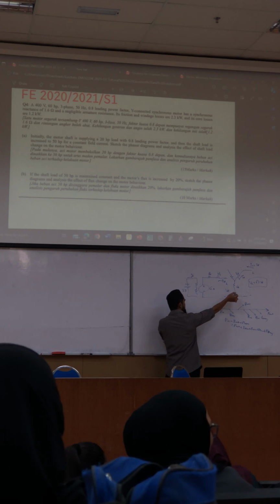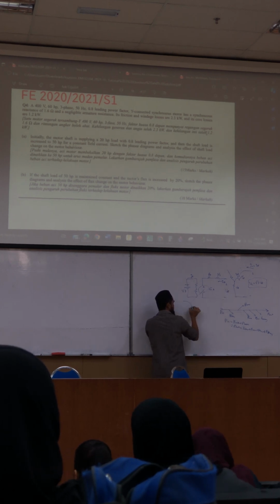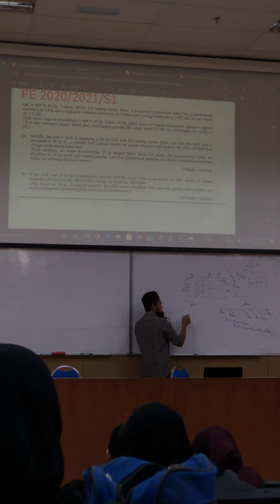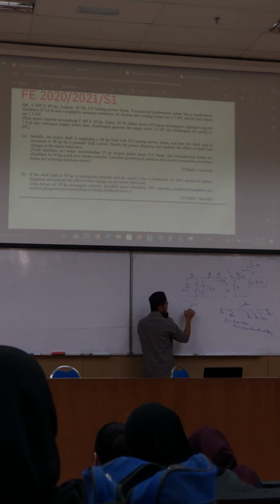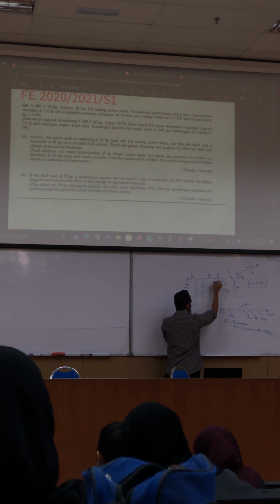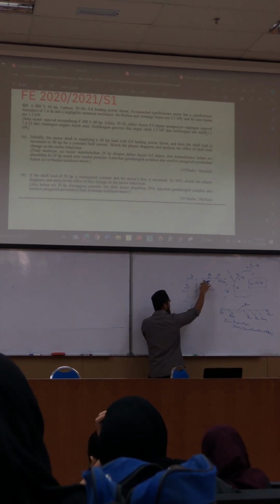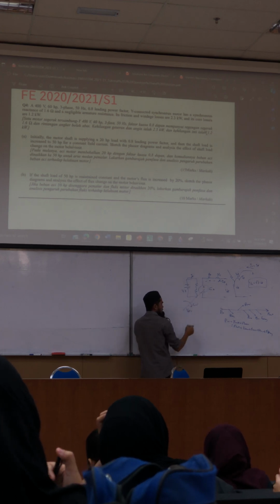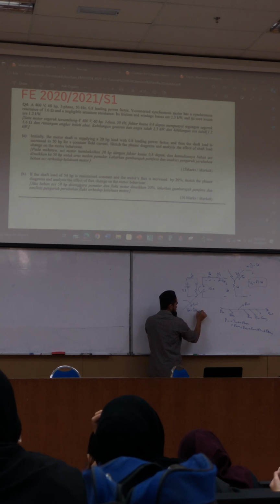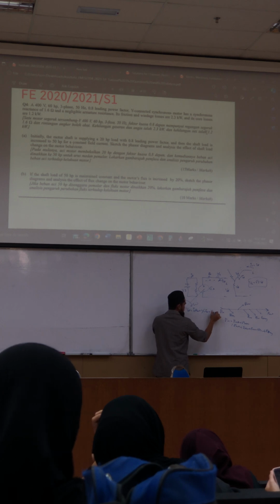With a motor we induce power, electrical power, so we get rotation. Electrical into mechanical. So the equation will be: your incoming is V phase. It drops across your jX_S, across your R_A, and across your E_A, equal to I_A R_A plus jX_S I_A plus E_A.